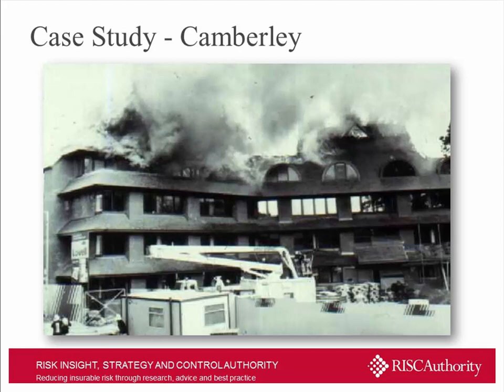The roof was lined with a mineral fibre insulation, but it was held in place by a reinforced plastic sheeting, a thermoplastic sheet with a paper backing. Having completed the work installing this pipe, which was done by touch welding using an oxyacetylene set, the plumber hung about, as he was required to do, and noted after 5 or 10 minutes that there was smoke about a metre away from him. He started taking some of the insulation down and saw that there was significant burning in the plastic and paper that had been used to line the roof space.